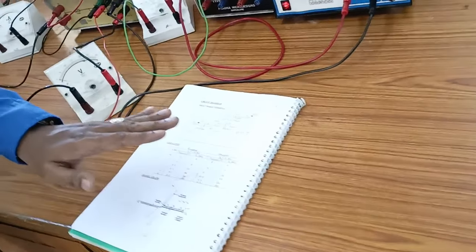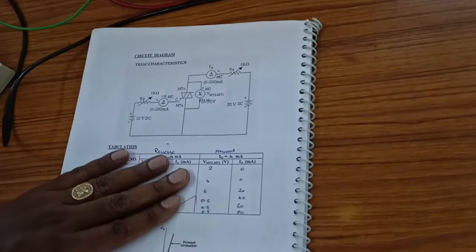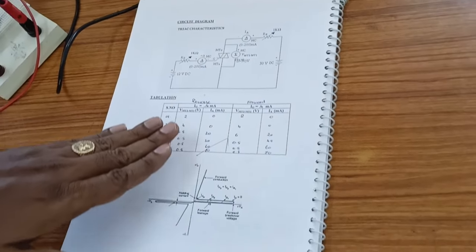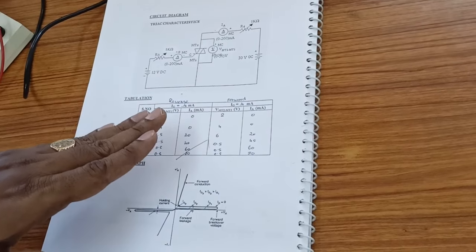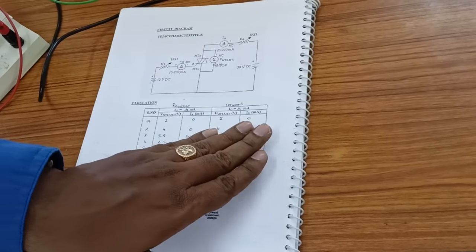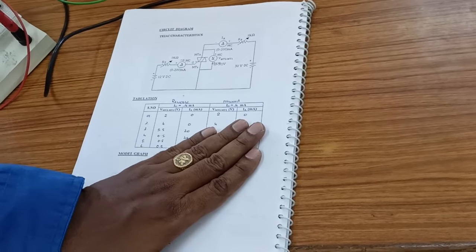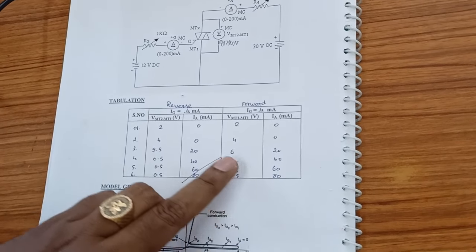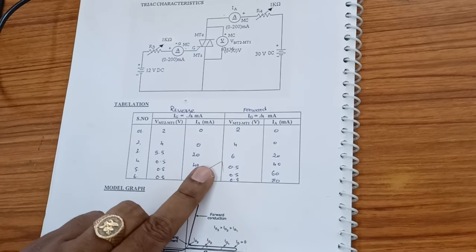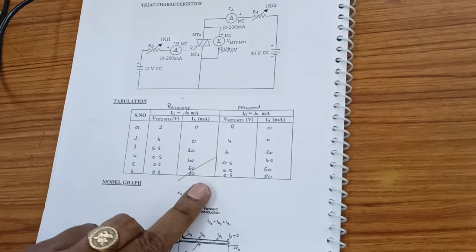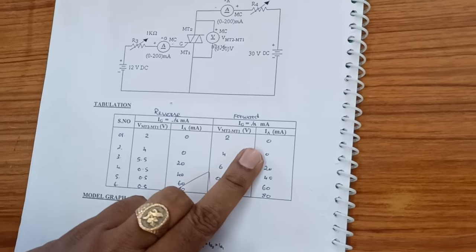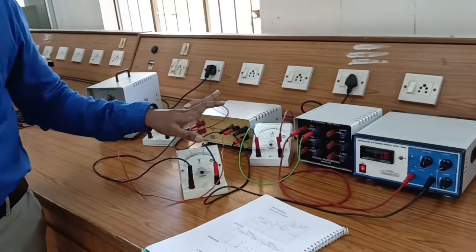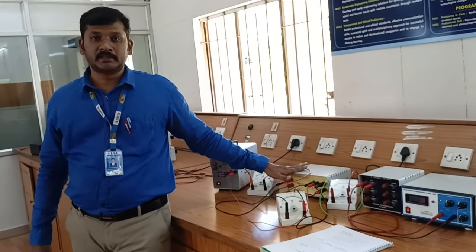For the different values of voltage, I am going to mark down the anode voltage and anode current of the device. I have to record these values, and I should conduct the same procedure for taking the readings for another value of Ig, keeping the values of the voltage at the same values. Only then can we see the difference in the ampere. You see that there is a variation in the gate current. So this is about the characteristics of our triac. Thank you.